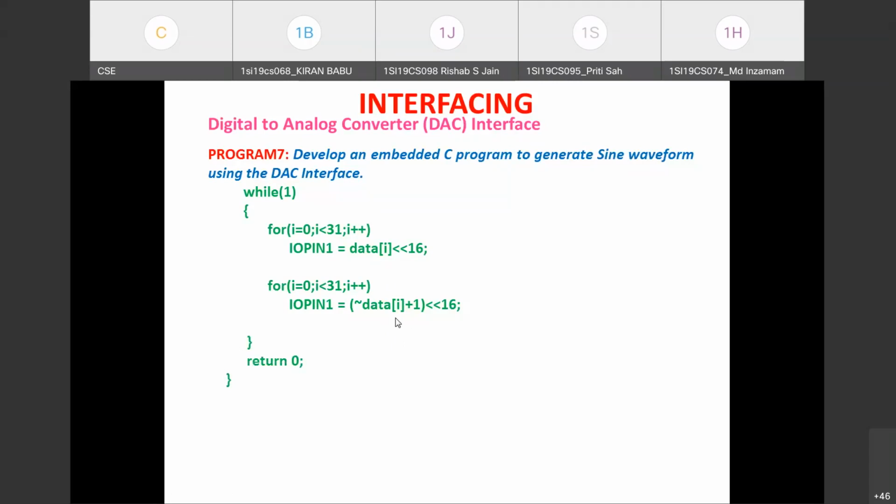So you need to use the digital formula 127 sine theta plus 127. Using that, you are calculating the discrete values for the sampling of the sine waveform. Only till 90 if you compute, that is sufficient. Same values you are going to repeat in the reverse order, so that you get the positive cycle values. If you just negate it and if you send each value, that will be for negative cycle.